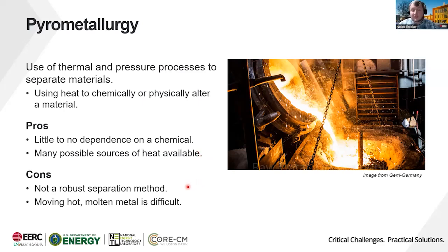However, it's not a very robust separation method. What I mean by robust in this case is it is not able to separate all the elements of the periodic table like hydrometallurgy can. Some separation can happen from it, but it's typically limited to either small separation effects or the really ultra pure separation, where in essence I'm removing 0.01% of impurity from a material, and pyrometallurgy can do that. But your common separations can't really be done this way typically.